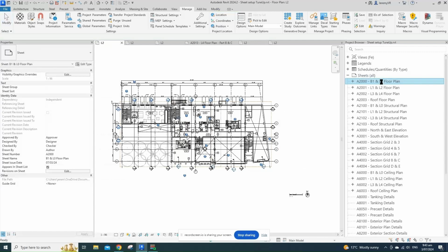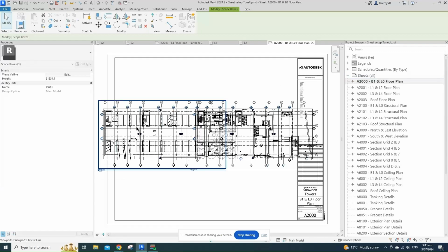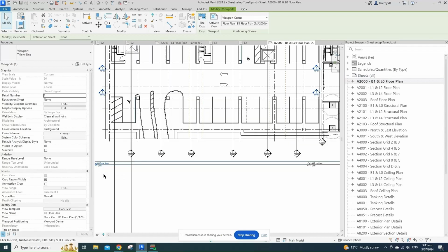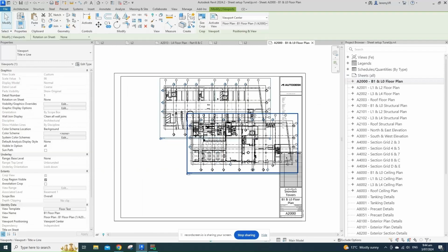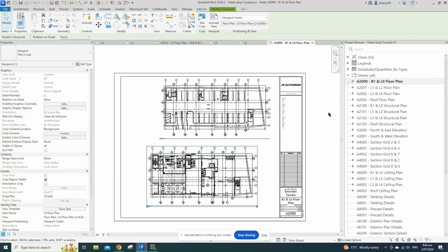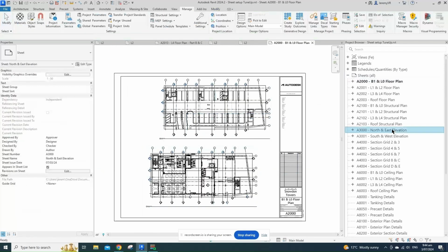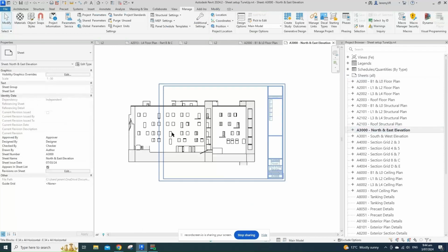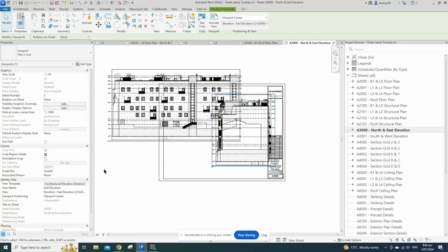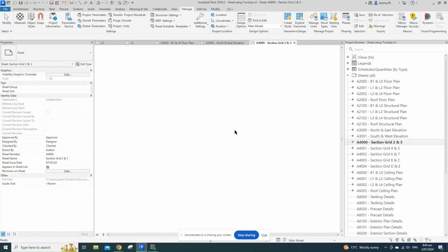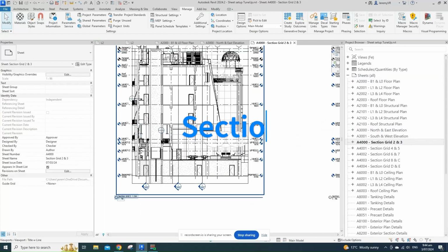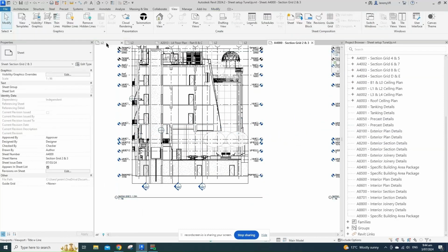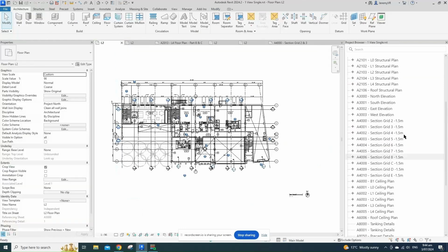For this example, we did two views to a sheet. And you can hop into your floor plan sheets, decide how you want them laid out, and then I would use another script to align sheets by template sheet. Then if we look at our elevations, they're all named correctly to the correct scope boxes. Our section view name includes the offset to the grid. Also, anything with ceiling in the name will have created a ceiling plan, not a floor plan.